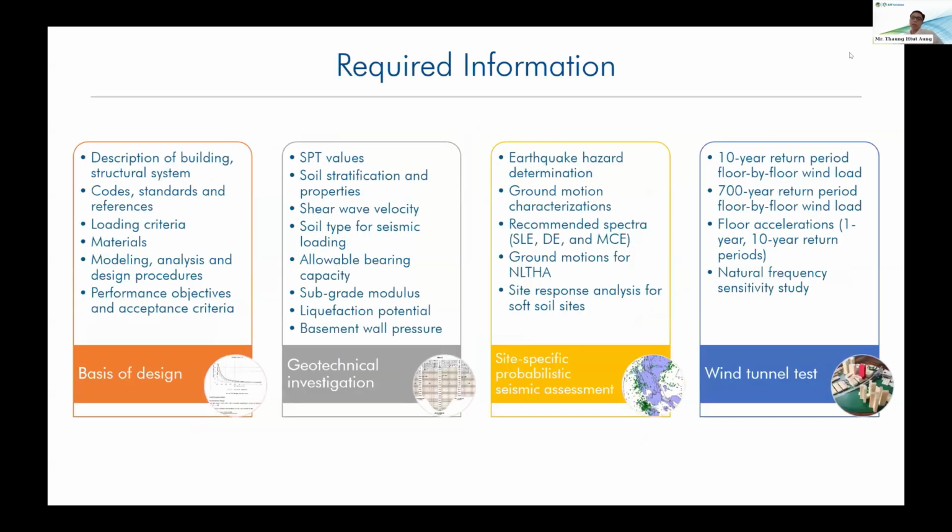To conduct PBD, we need additional information compared to the building code-based design. First, we have to prepare the design criteria. That part we normally prepare in the code-based design as well, but we need to add additional items in the design criteria considering the nonlinear modeling procedures and also acceptance criteria for different levels of earthquakes.